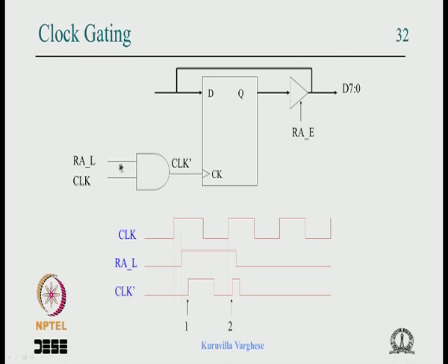So you might think that you can add 2 inverters to get that delay, but then you know that this delay depends on the clock period, and if you add arbitrary delays and change the clock frequency, it doesn't work. And you know that the delays are a function of the temperature and the supply voltage and so on. So if in the slowest path you introduce a delay, and when it becomes fast this may not work and so on.